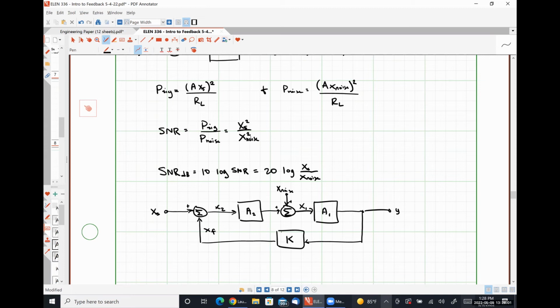So for you guys that do a senior design project based on some type of audio amplifier, I would beg you not to test it upstairs in the circuits lab, where 60 hertz hum is going to be coupled to effectively any and everything you could do, which is what has happened in numerous other senior design projects here, because this building is not grounded particularly well.